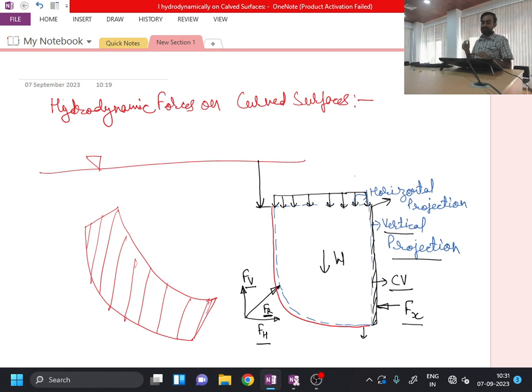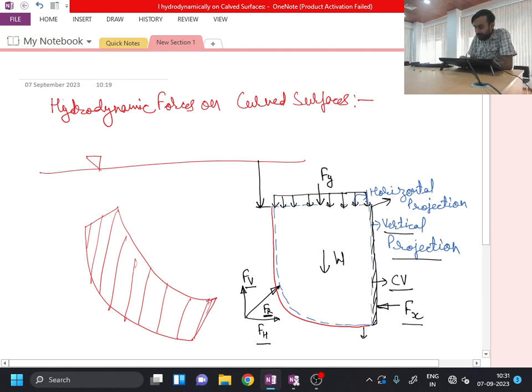So as we are not changing the elevation, at each and every point the magnitude of the pressure will be the same. Okay, and say this is contributing to some resultant force Fy over here. Now we are considering this control volume of the liquid. This particular control volume of the liquid will have a certain amount of weight also. So say W is its weight.